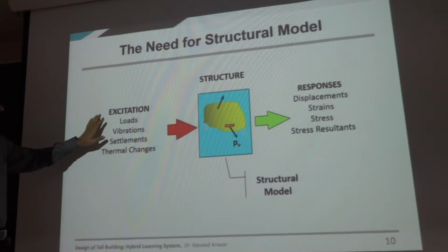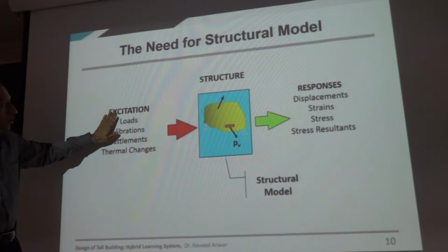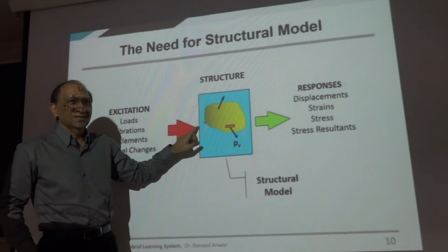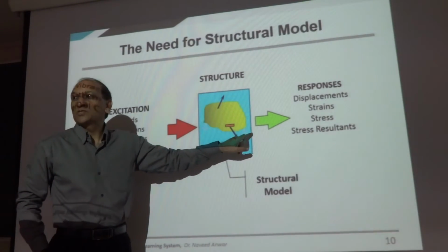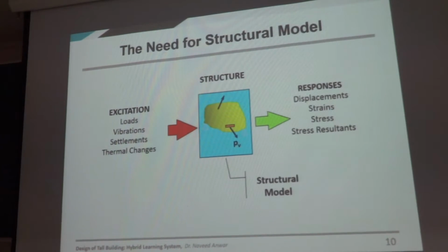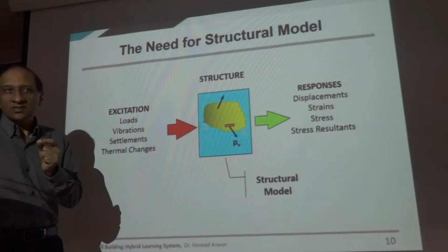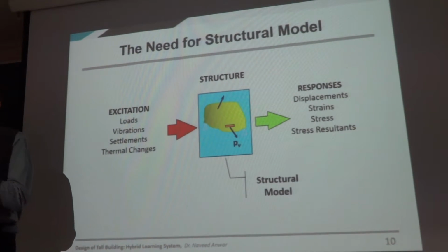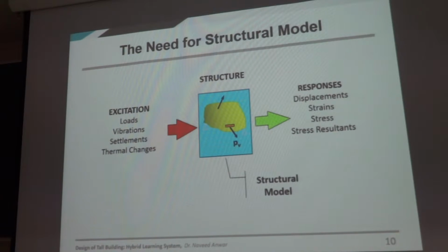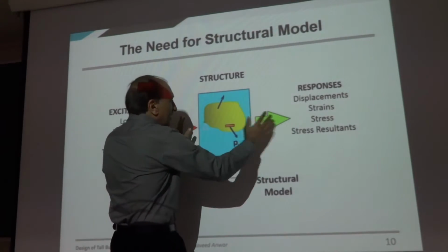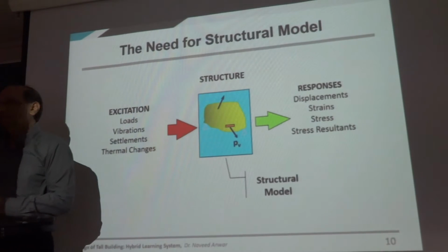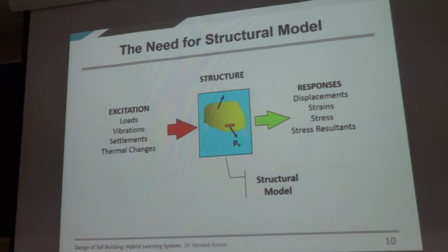So then the excitation and loads are applied not to the structure, but to the model. And the response that you get is for the model, not for the structure. This is one of the most important things that you need to realize. Don't say, I am analyzing the structure. You can never do that. You are always analyzing a model of the structure. So if your model is not good, the response is not good. The response may be very good for the model, but it may have no relationship with the structure.